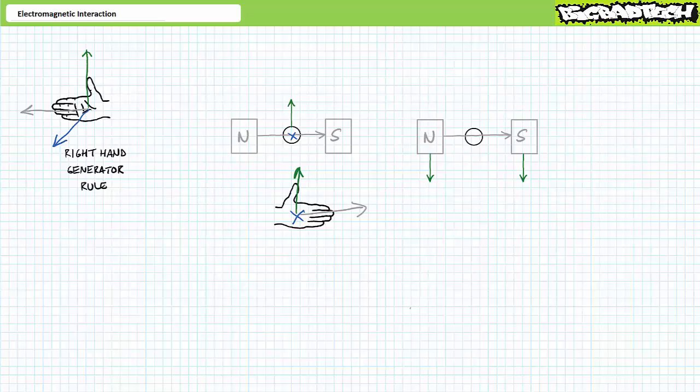In fact, both the magnetic field and the conductor could be moving in the same direction. As long as they move at different speeds, there will be a change. As an example, asynchronous generators, a subject we'll examine at length in later lectures, have a rotating magnetic field in the stator, and the rotor is rotating at another speed. As long as the rotor exceeds the speed of the stator, there's relative movement and generation can unfold.